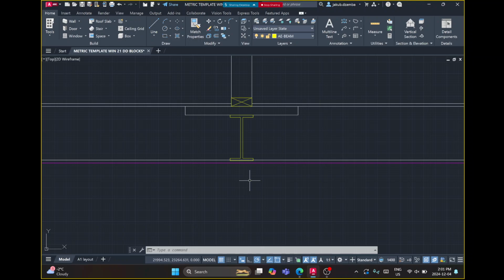So basically this is 100 millimeters across. And then the width of the steel is 10 millimeters. So I went 10 down, and instead of going 50 back to get to the center, since this is 10 millimeters wide, I just went 45, 180, 45, 10, and so on.